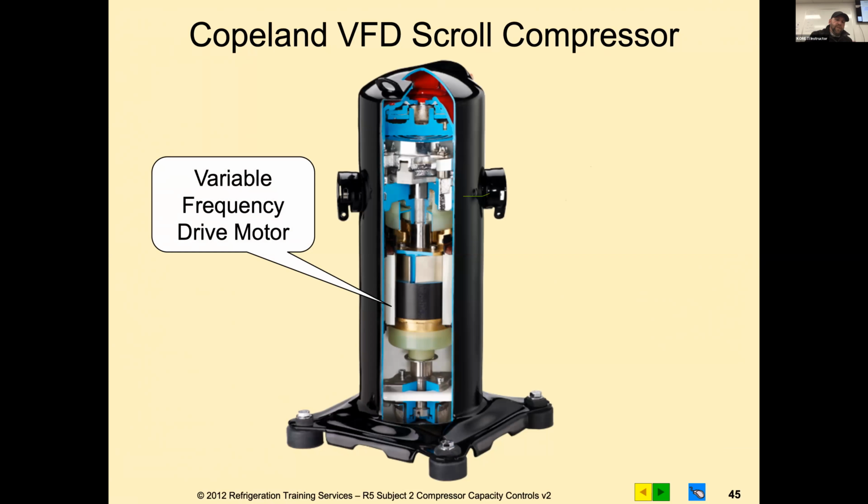Usually what you'll see is we'll hook up what's called a Y valve, and it's only called a Y valve because the model number starts with a Y. It's a modulating, mechanical valve, and you put the temperature probe down inside the top of the scroll. It modulates how much refrigerant it flashes into the chamber to desuperheat that compressor. So yes, it's the same. It's a capacity control, to help with the compression ratio and cool the compressor.